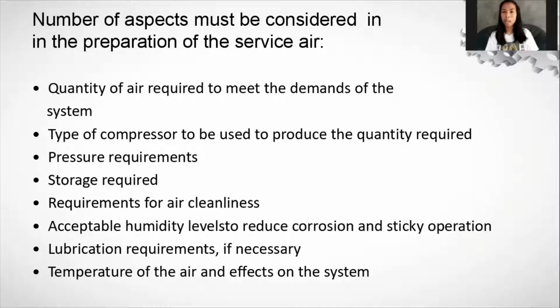A number of aspects must be considered in the preparation of service air. Quantity of air required to meet the demands of the system, type of compressor to be used to produce the quantity required, pressure requirements, storage required, requirements for air cleanliness, acceptable humidity levels to reduce corrosion and sticky operation, lubrication requirements if necessary, temperature of the air and effects on the system.